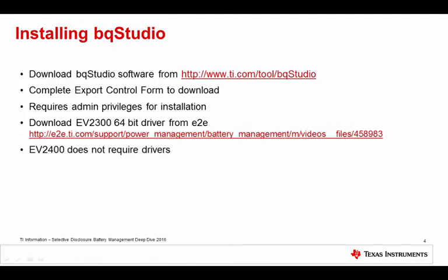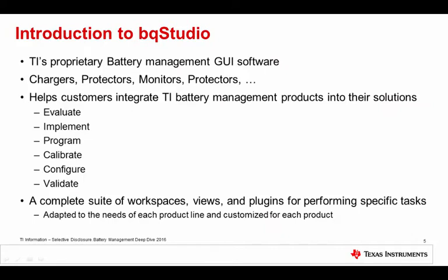There's a standalone, should you need it, EV2300 64-bit driver available through E2E. There's a link up there, but also I'd search for it on E2E for the location, because that's not a permalink. So if you're using the EV2300 in a 64-bit environment and you have administrator privileges on your system, there's a standalone 64-bit driver for support for that, should that be necessary. But most of what we do today going forward is around the EV2400, which doesn't require any additional driver support in Windows. It just works as is.